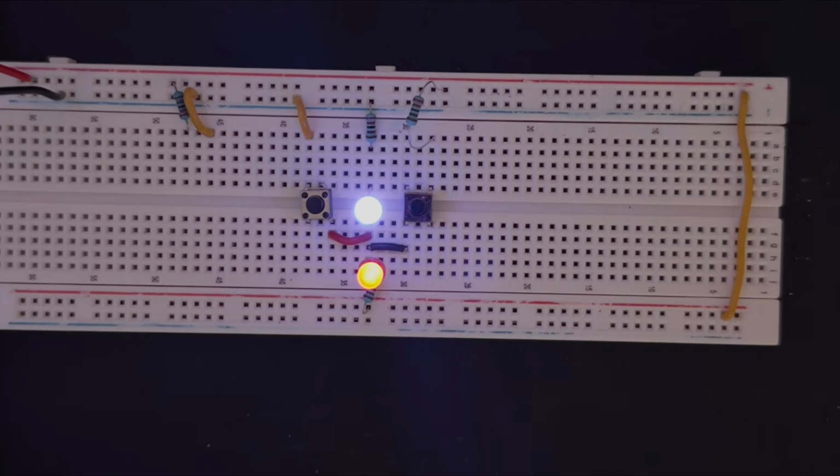And we have a nice visual that represents this. If I add 2 LEDs to this floating wire, they basically tell us what state this middle wire is in. Right now, we can tell that the wire is floating because both LEDs are dimly lit.